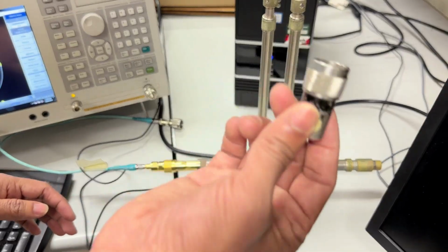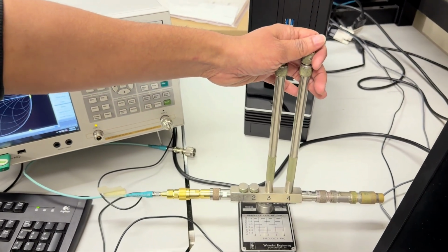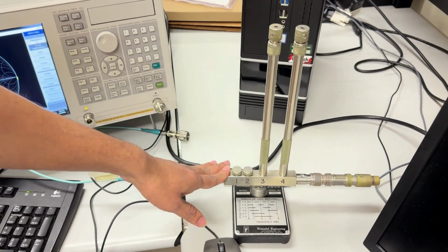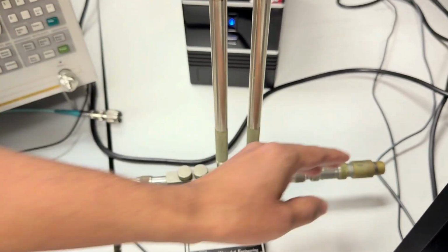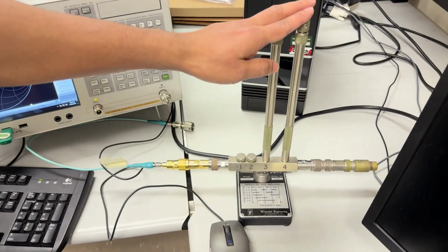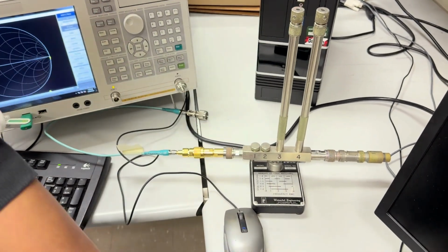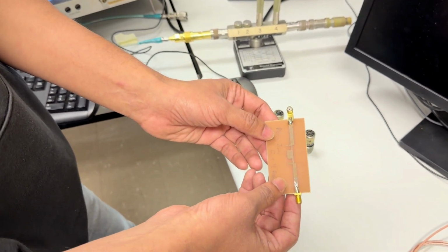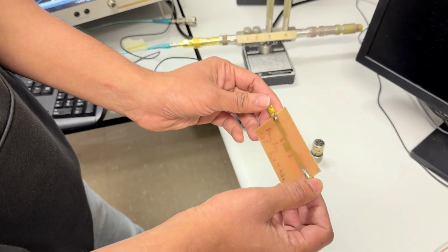So I talked about the 50 ohm impedance. This is called a double stub tuner. Basically, this device is used to facilitate the matching, called impedance matching, of an antenna. For example, if you have a source or load other than 50 ohm impedance, we use the stub tuner so that we can achieve that 50 ohm impedance. You will also be using this low pass filter, designed with CST and fabricated using the printer. It has 2 ports here, and we will characterize this one as well.